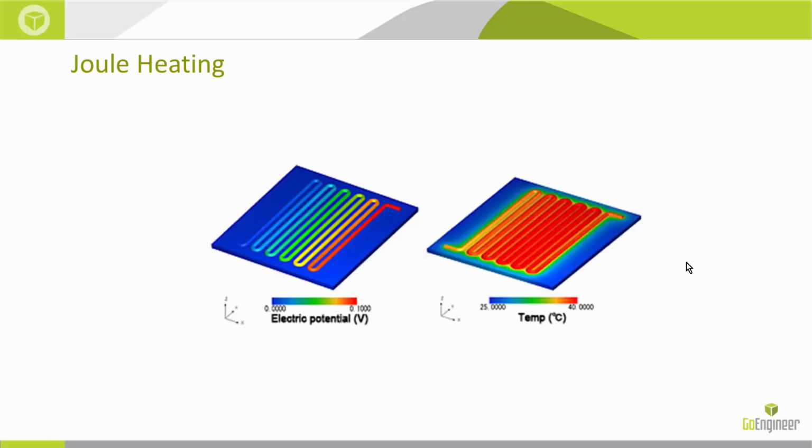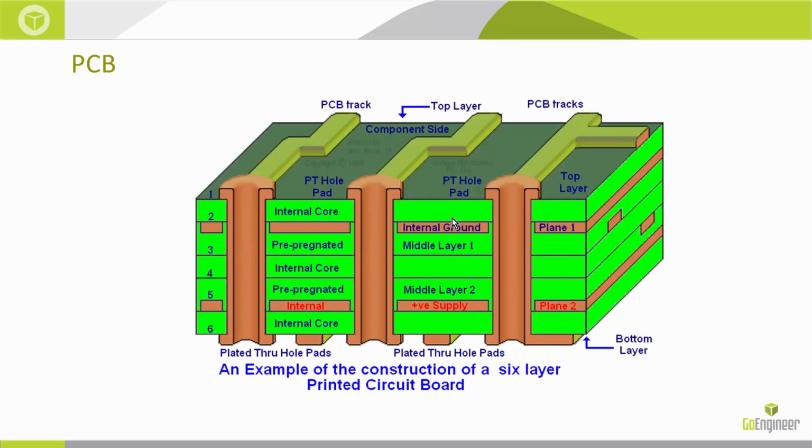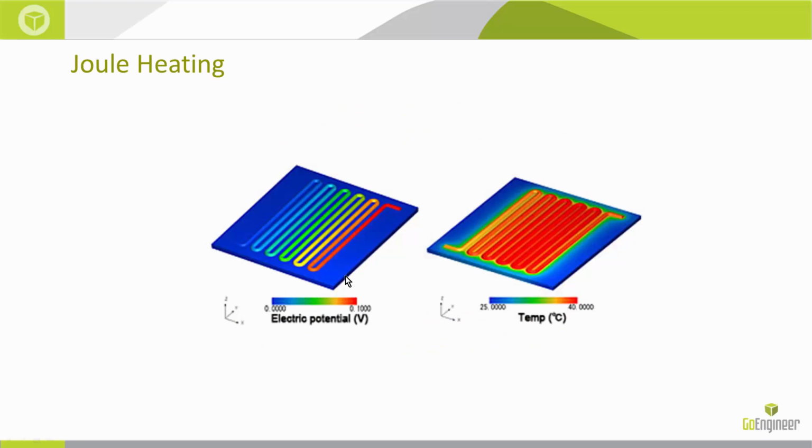Alright, final thing we have is electronic conditions, most commonly used when we're talking about joule heating. In this case, we could see how much heat is getting produced because of current. What's important to know and remember is to have a high density of elements across wherever you've applied the electrical condition. So I would say 4 to 5 across the diameter of this wire.